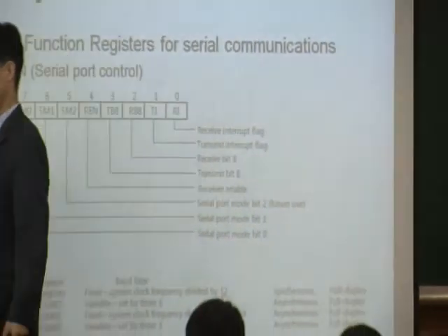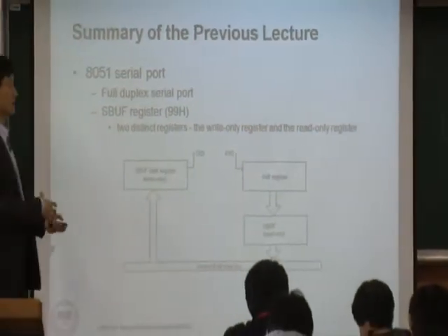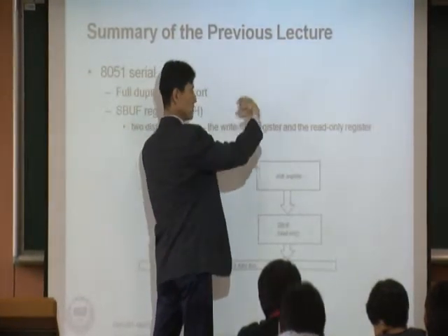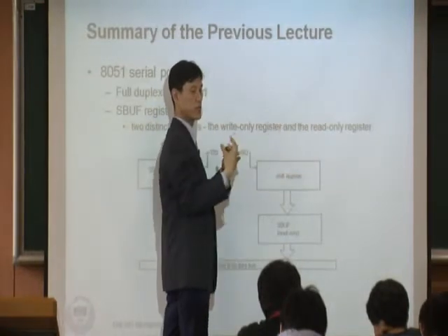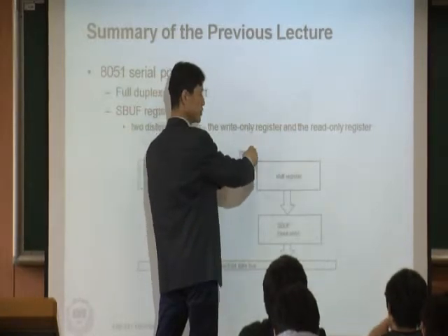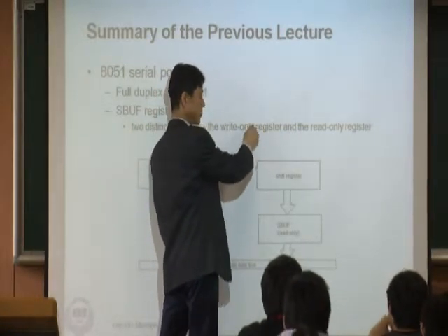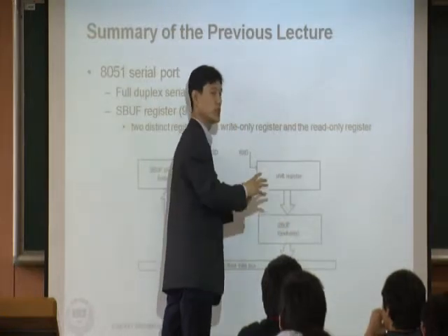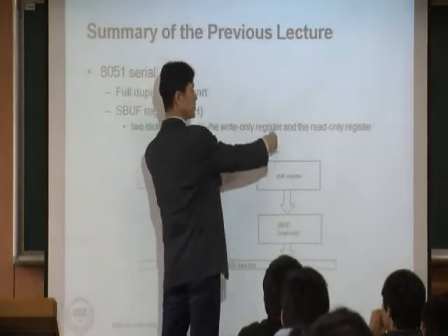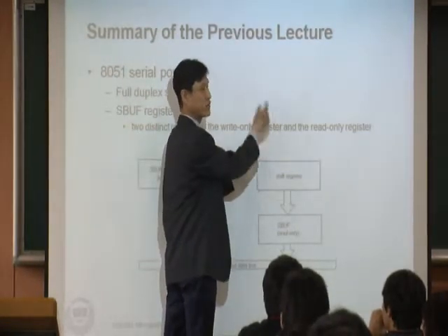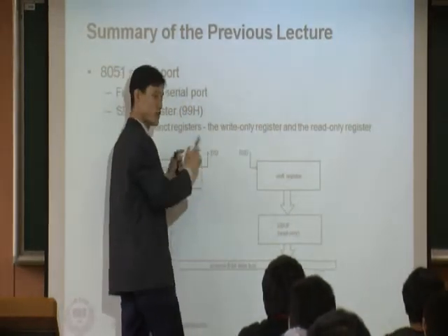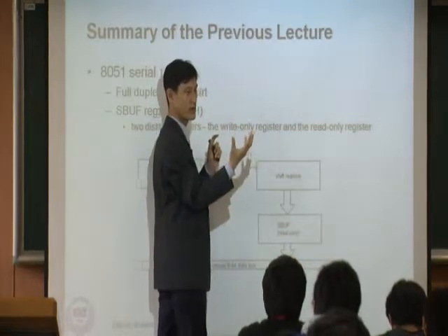That's the transmit side. Let's look at the receive side. In the receive side, it's similar. Here's what happens: some external device is transmitting value C to you. That value comes to your processor, and that C automatically goes to SBUF by the hardware. What the hardware has to do is receive a certain packet, including C. Again, you are transmitting a packet, so of course you are receiving a similar packet.